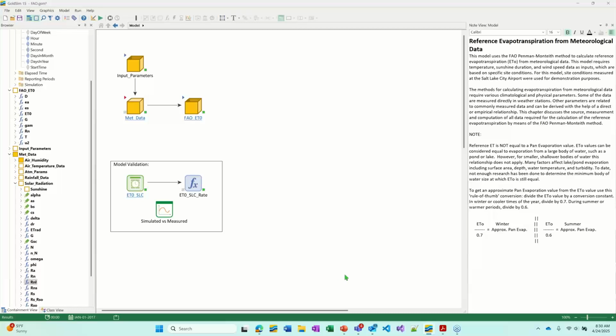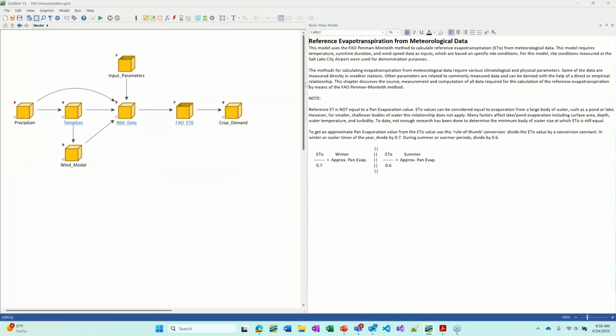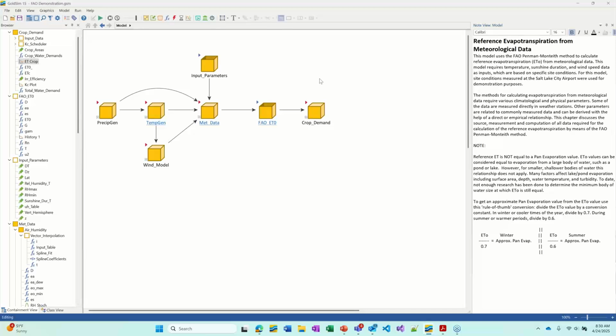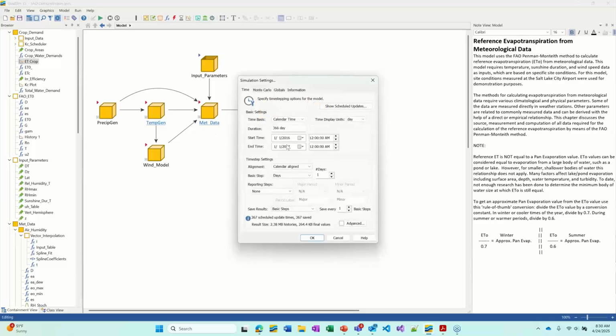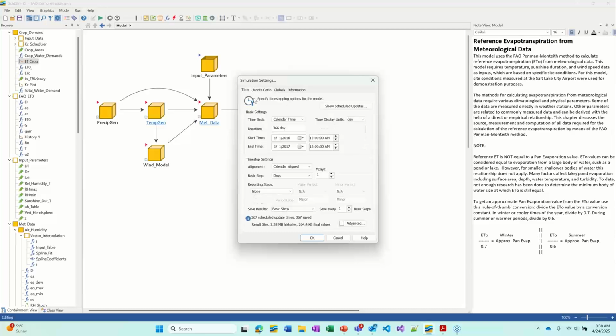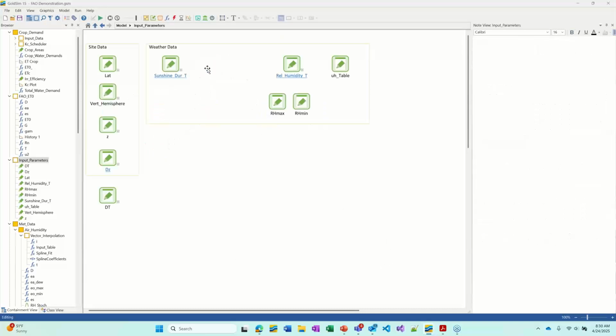And now what I'm going to do is shift gears over to a demonstration where I've incorporated daily data. And like I said, just let me know if you have any questions. But I will be posting this recording and also this model. Okay, so here's the same model, but what I've done is, first of all, I set this model up to run Monte Carlo, 100 realizations. So we have randomness now in the model. And instead of relying on temperature time series, I will be simulating temperature.